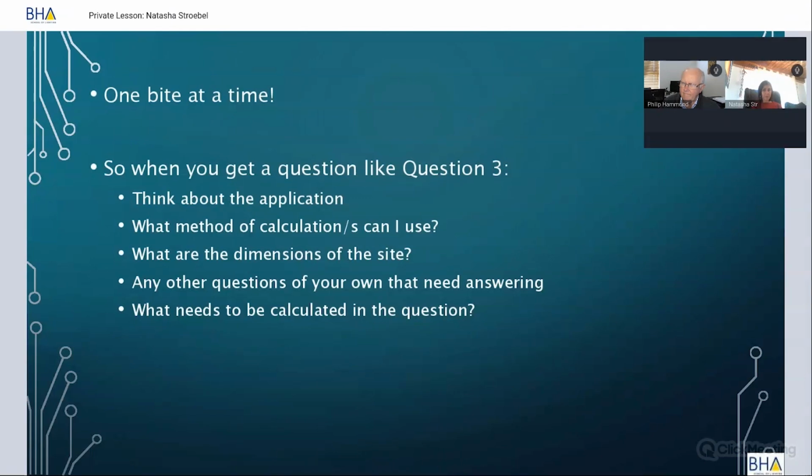The point method. Correct. Why? Why don't you use the Lumen method? Because the Lumen method's only for indoor applications. And there's no box in this one. There are no walls. Correct. Yes, there's a floor, but there are no walls. So the box doesn't exist. Okay. Yes. So I'm trying to help the reasoning.